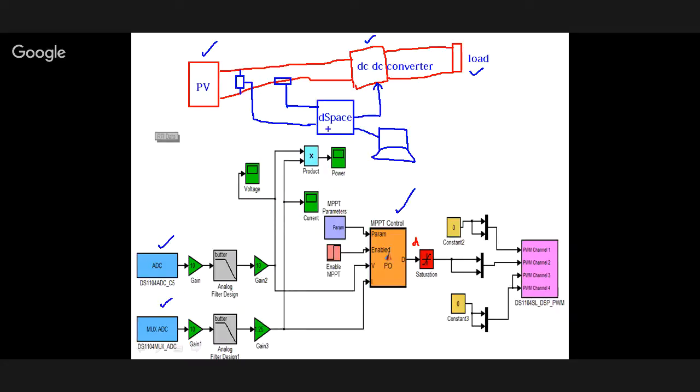Okay, and now from there it comes into the MATLAB environment. This is inside the MATLAB environment. Actually, I am defining a port here, analog to digital port 5. I am taking it into channel 5, and I am taking this into the first mux, into 1.